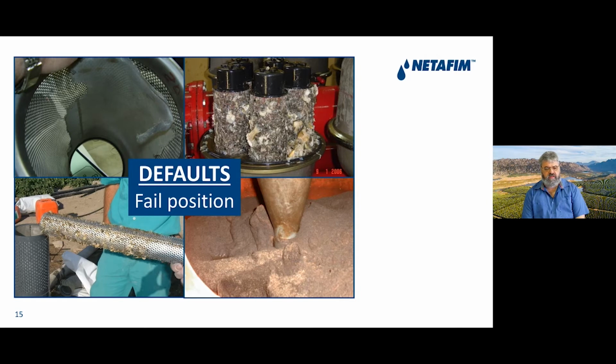If you look at the photo at the bottom, you will see the dirt that was pushed through the screen and is sitting on the outside, where your system will actually be. This will be for two reasons. It can be that your filtration screen collapsed, like the picture on the top, or if you have too high velocity through that screen, you can also get similar results.